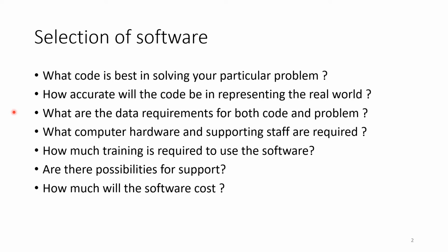Know that the parameterization of the models might slightly vary across codes. MODFLOW, for example, usually goes by hydraulic conductivity and aquifer thickness. Others will operate on transmissivity directly. So codes vary, but that's something where you can recalculate one value from the other by hand. But still, there may be slight variations.